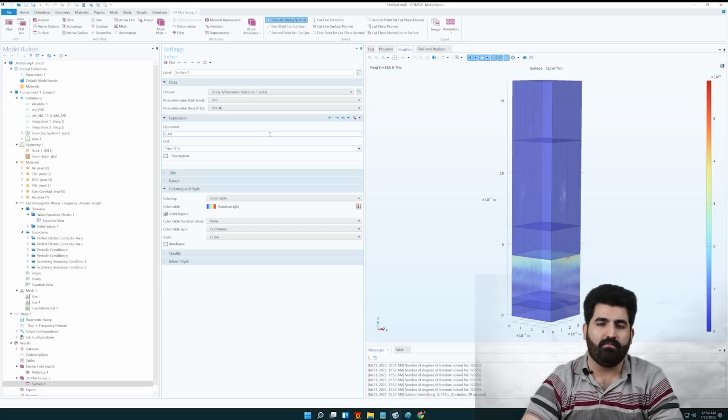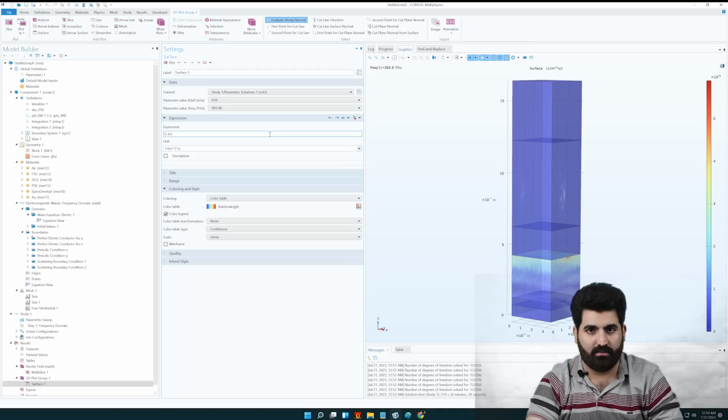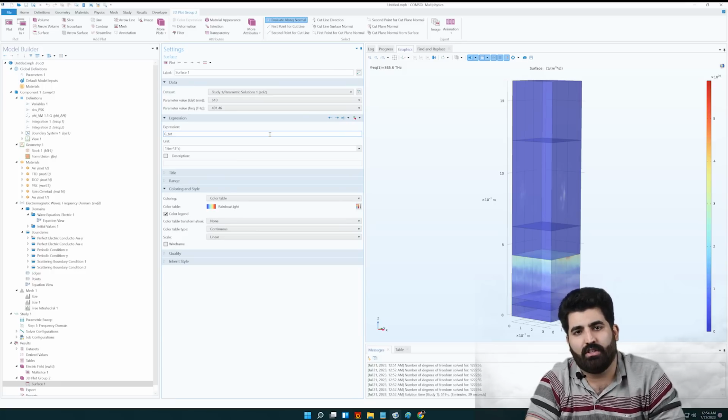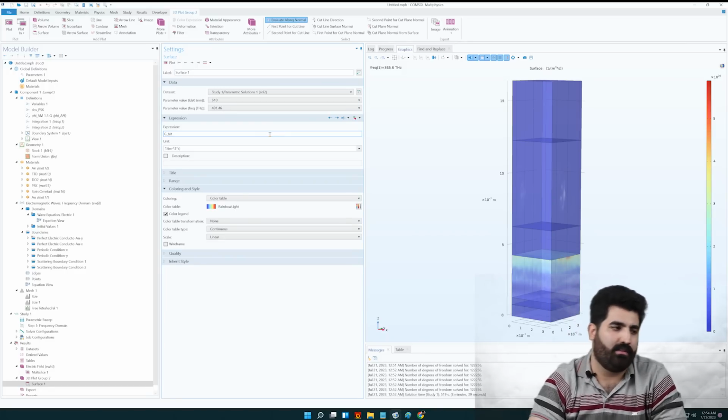After summing all of this wavelength generation, you have a total generation for using your semiconductor properties or electrical part to do your IV curve and calculate your efficiency, fill factor, short circuit current density, and also open circuit voltage.